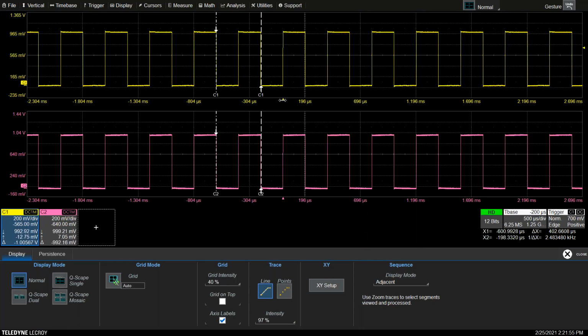So that could be totally off screen if you want, and you can still make measurements. It will tell you the timing from the trigger point. We are triggered on an edge trigger, by the way, on channel 1. In this case, it's 700 millivolts positive. Okay, so this is this timing, and I'll move this along a little bit more. You can see that our calibrator signal, I set it to 2.5 kilohertz as its output. Okay, and then you can obviously go to amplitude cursors.